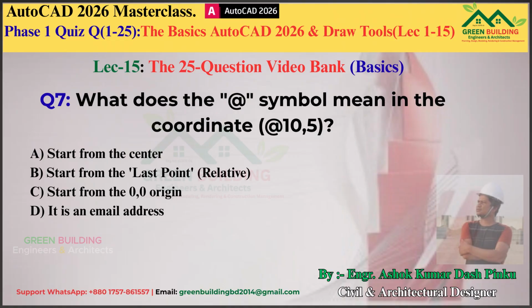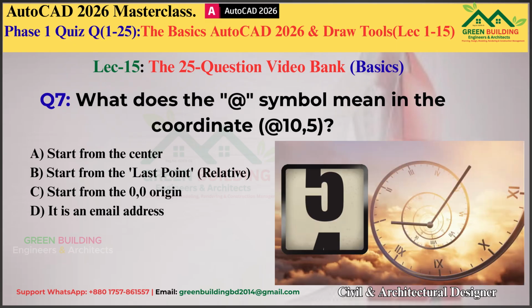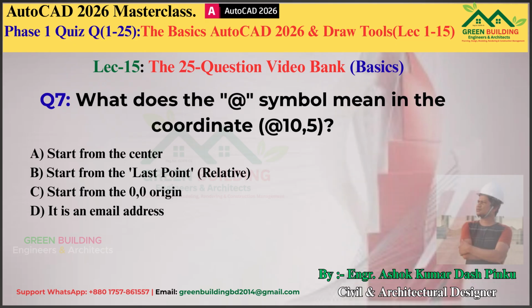What does the at symbol mean in the coordinate @10,5? Option A, start from the center. Option B, start from the last point, relative. Option C, start from the 0 origin. Option D, it is an email address. The correct answer will be B, start from the last point, relative.